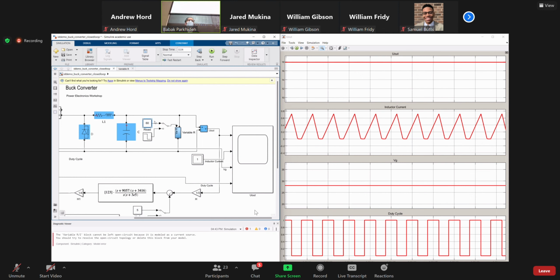Okay. I assume it's because there's a point where you're not having losses across the switches. Because at that point, when the current hits zero, the other switch starts at zero. Do we have any switching losses when a switch or a diode starts from zero? No, yeah, that makes sense. No. Or at least not a lot.